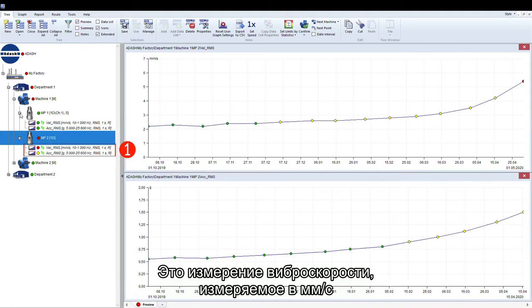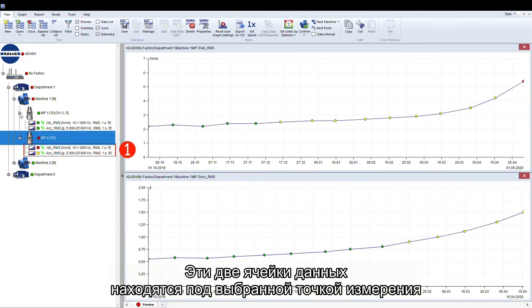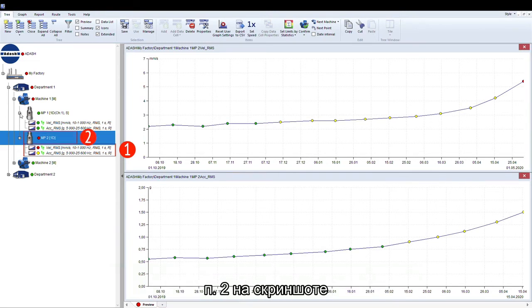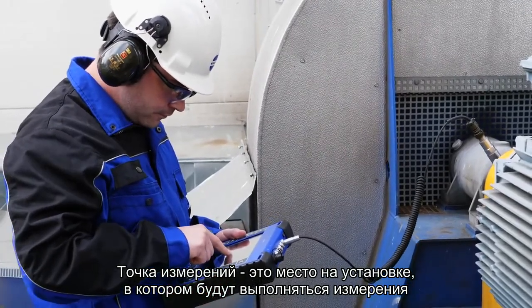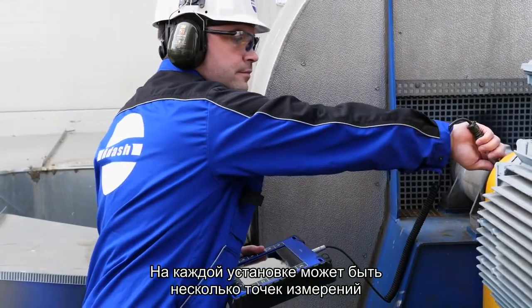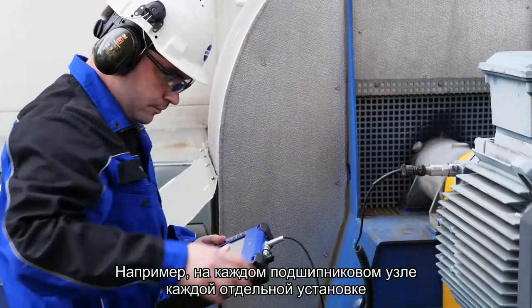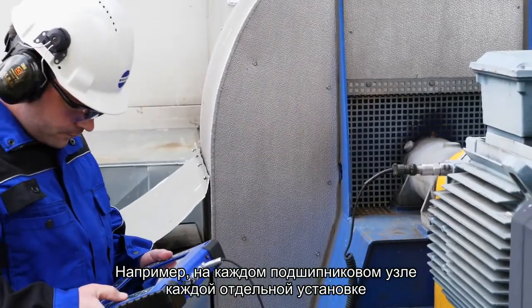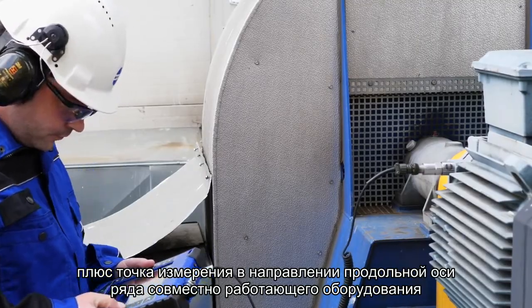These are velocity in millimeters per second and acceleration in g measurements. These 2 data cells lay under the measurement point, item 2 on the picture. The measurement point is the place on the machine where we will be taking the measurement. There will be more measurement points on each machine, for example, on each bearing housing of the machinery component, plus 1 on the axial direction on the machinery set.